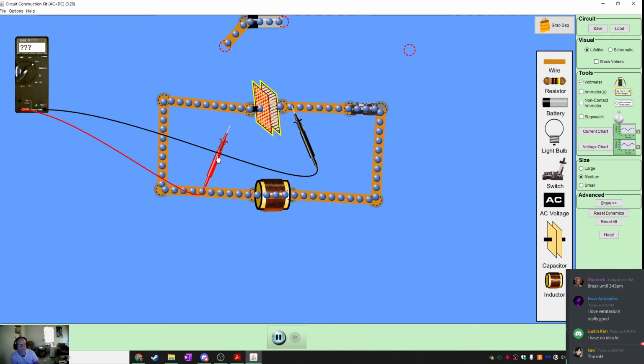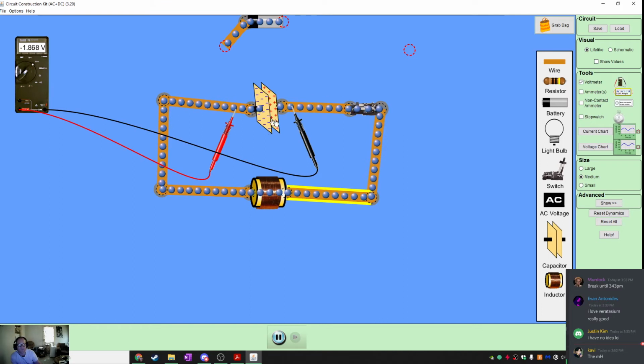That's kind of cool. Can you see how this capacitor here is almost acting kind of like a spring for these electrons? Like a springboard? Maybe the word spring is the wrong way to say it. Maybe more like a trampoline. It's like the charges flow into it until they can't flow anymore, and then they get shoved back in the other direction until they can't shove anymore, and then they get shoved into the other side. And then they start to push back because there's an electric potential that pushes back. And normally that would stop, except the current has to keep flowing because this won't let it stop. So that's your LC circuit. I find this to be really fascinating.